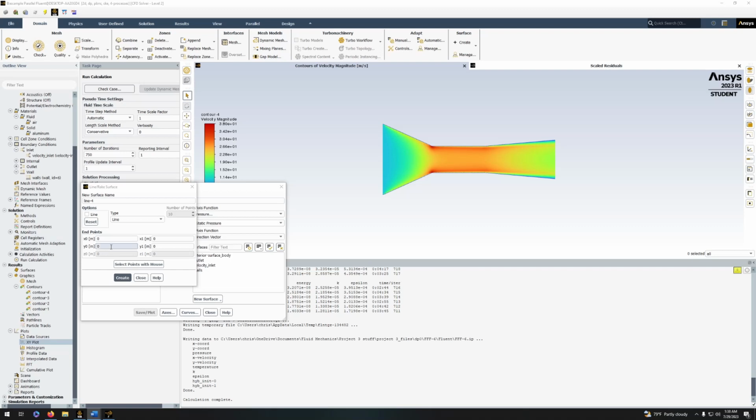Okay, we'll make the y, I'm sorry, the y values are going to be 0, the x values are going to be 1.95575, and this one's going to be 1.95575. So this one's negative because it's going all the way back this way. The origin's going to be right about here. And then this one's going to be positive because it's going this way. So then we'll call this center line. Okay. Create. Oops, created two of them. That's okay.